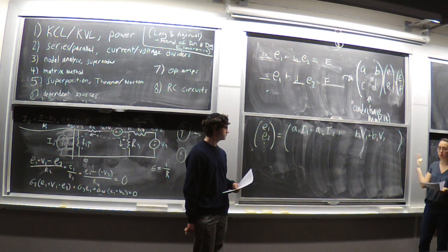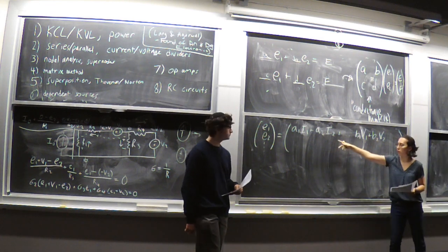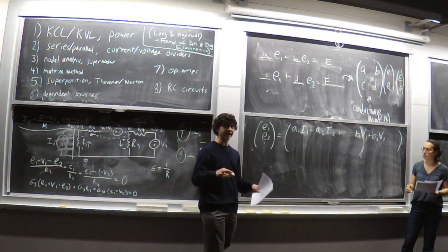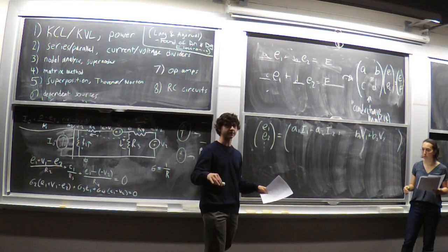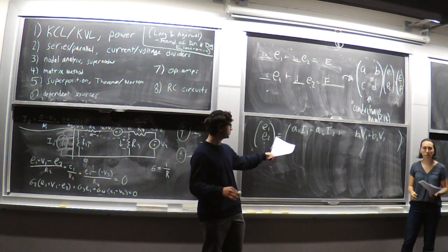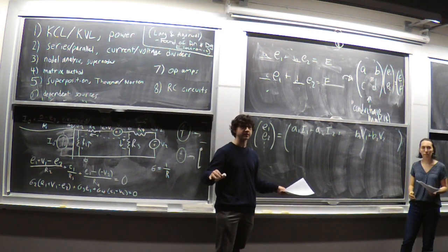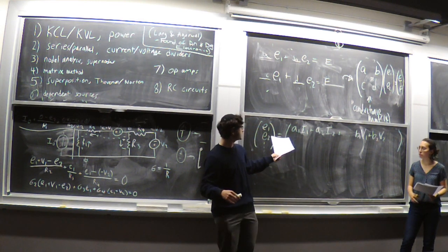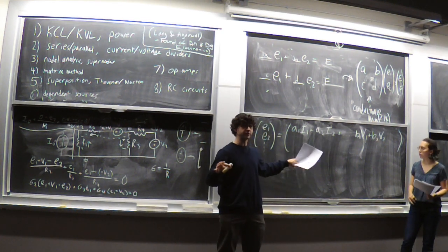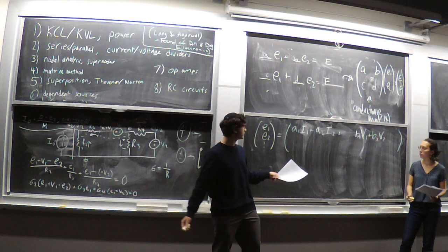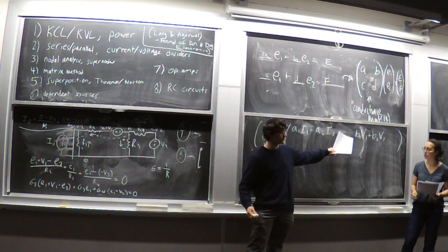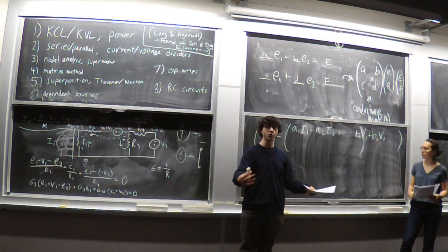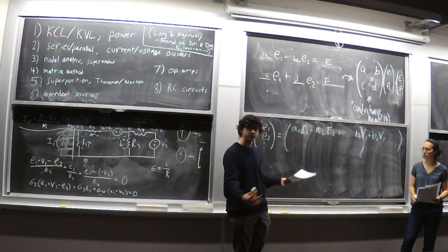And so when we do that matrix multiplication, we're going to end up with some sort of thing that looks like this. And the key here in terms of being linear is that we're not multiplying any of the different independent source values together. You're never going to have I1 squared or I1 times I2 or I1 times V2 or V1 squared or anything like that. All of them are just going to show up as their own terms with constant coefficients. One other thing to note is that the A's and the B's here have different units. It wouldn't make sense to add a voltage to a current. So because we're solving for voltages, all of the B's will just be numbers, no units, whereas all of the A's will have units of ohms, like resistance times current equals voltage.